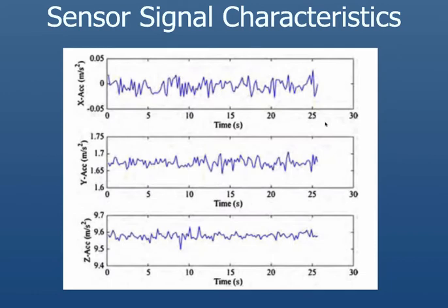In general, signals acquired from sensors are either weak and small in magnitude, or contaminated with noise, or both. For instance, the original voltage readings generated by a thermocouple are in the range of microvolts, making it difficult to process via a DAC system without appropriate amplification and other types of preconditioning. Similarly, the signal generated by an accelerometer is typically very noisy as it is.